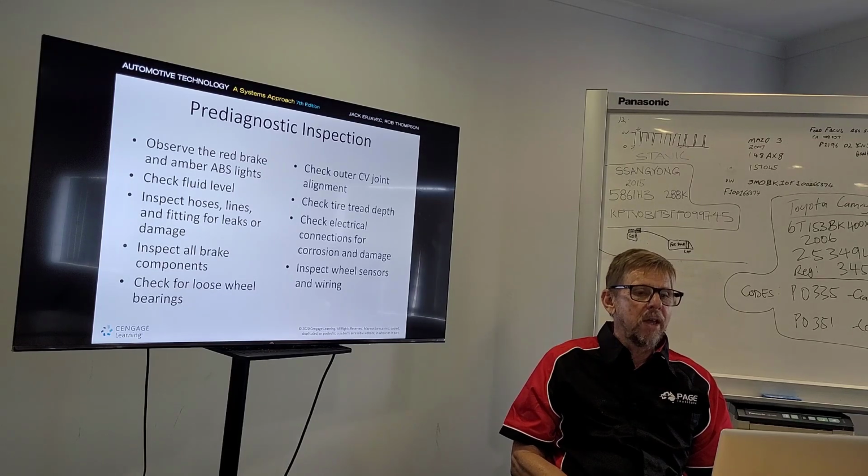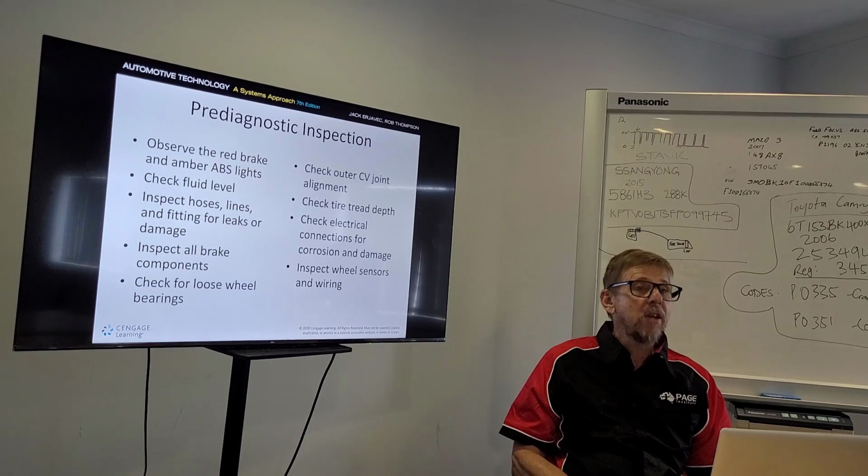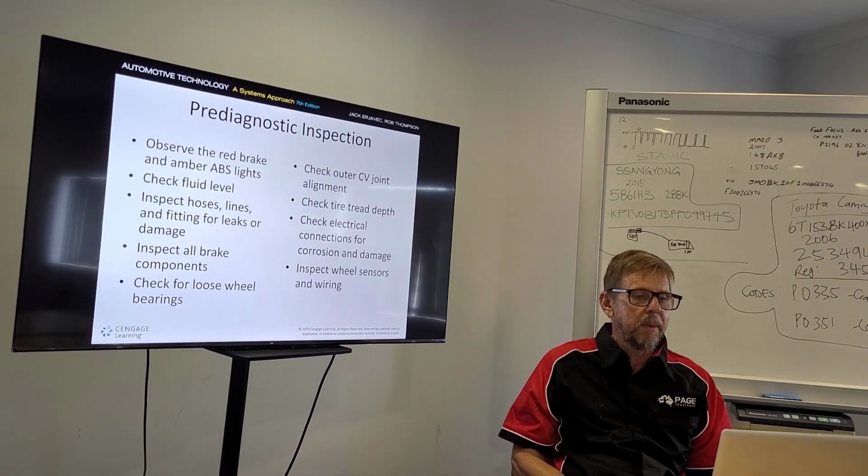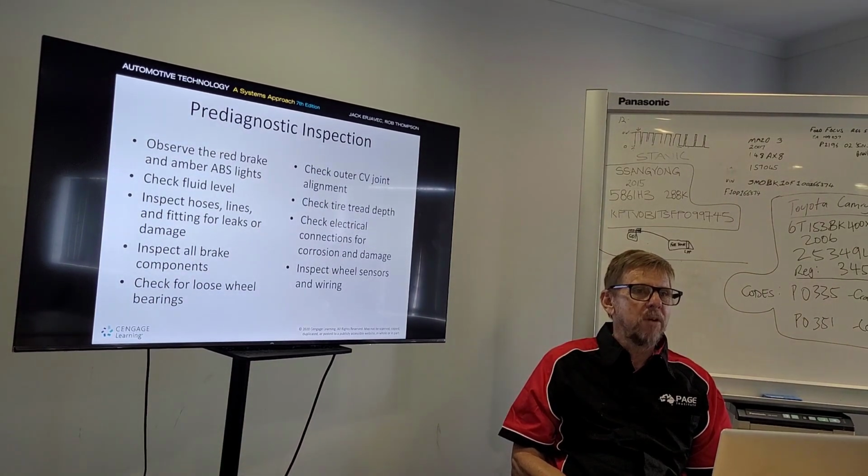That simple. So yeah, it's important to check your fluid levels. Check your fluid condition too, if it's contaminated, that can tell you a lot. I mean, if we're doing an engine diagnostics, we always check the engine oil. We always check the coolant level and the condition of both coolant and engine oil.